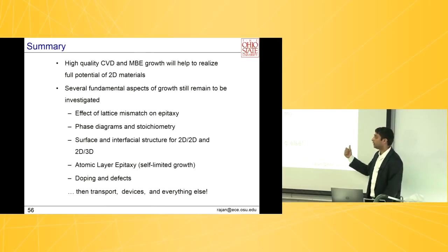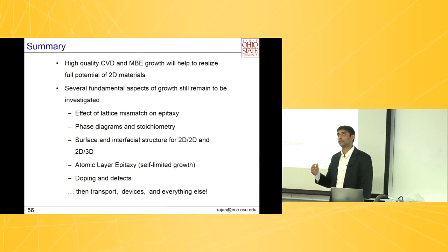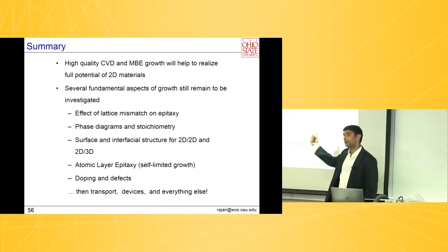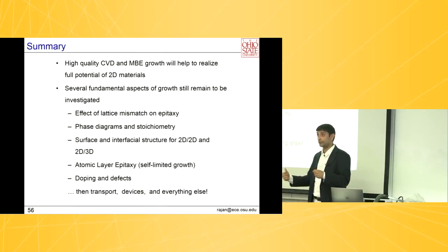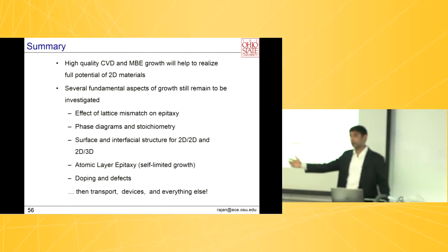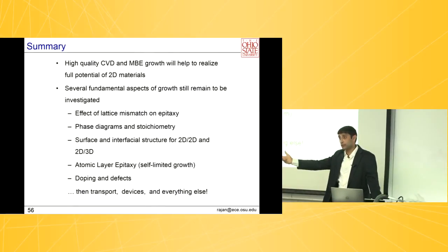I think the question is a risk of adsorbates causing unintentional doping. Now, I think in the paper, the potassium doping was intentional. They put potassium to actually dope the material. What I was concerned about is the long-term stability, because if you have to actually make a device technology, you have to do passivation, you have to do metal contacts, those kind of things. I don't know how compatible that's going to be with other device technologies. But I think it's a very interesting way because you can put the doping wherever you want, kind of like ion implantation. So it's very interesting, yeah.